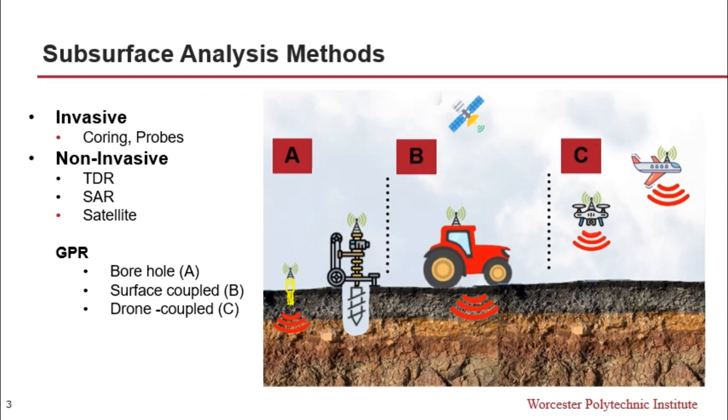Subsurface analysis methods can be categorized into two main categories, invasive and non-invasive. The invasive methods, which include coring, using probes and excavation, and then sending the samples to the laboratory for more in-depth analysis, are simple and accurate, but they're destructive, time-consuming, and in many cases expensive.